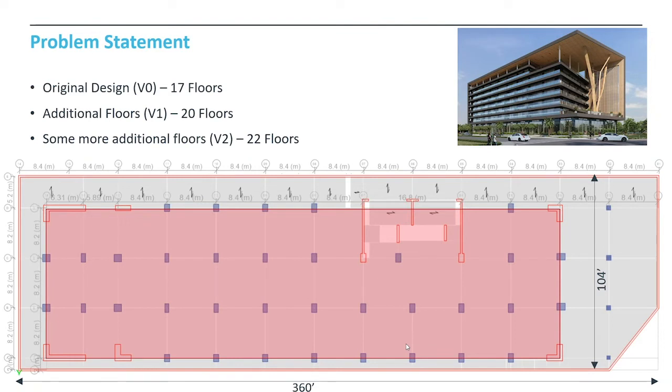Yes. So the way it worked, we started working on the model given by them. We modified the cross sections, added those to the model, and then supplied the same ETABS model back to them. They checked deflections and other global checks, whatever they thought appropriate, and then they supplied it back to us, because while we were strengthening the elements which were already constructed, they were also doing the same thing, but their elements were still not constructed.